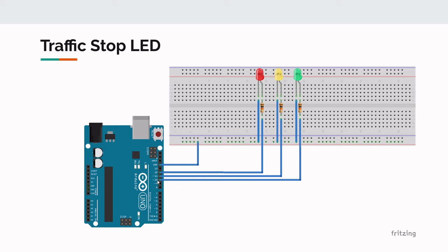Now, let's follow one of the LED currents to find out how it works. So number 10, it goes through this wire and it goes through the resistor to reduce the amount of voltage that's going to go to our LED. After this, it comes in through the anode, out through the cathode, and to our receiving line, which will come back to the ground. Now the same logic applies for the rest of the LEDs, and we have a working circuit.